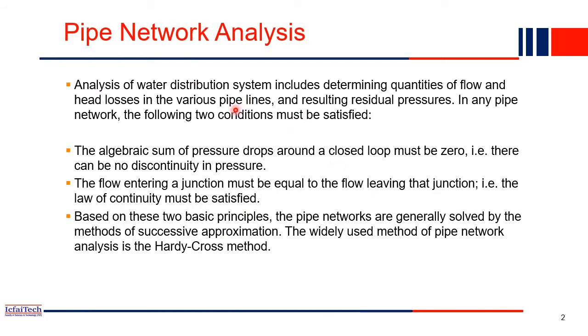We will do pipe network analysis, and then we'll identify how much flow is required and what the dimension of pipes is. Pipe network analysis of a water distribution system includes the determination of the quantity of flow, meaning how much flow will be passing through the network.